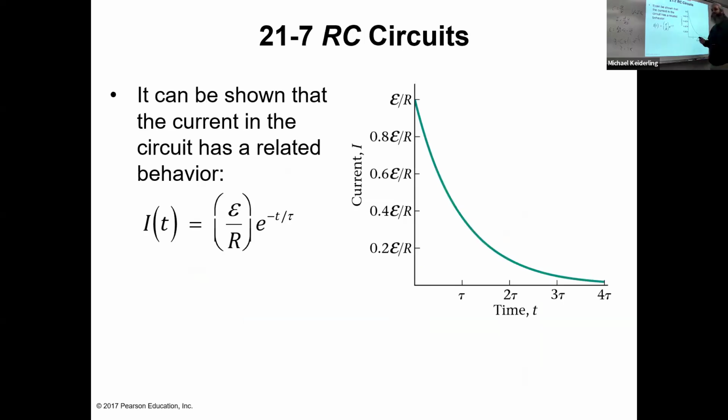And so you can set up situations where you have one thing with a relatively high resistance that charges a capacitor up slowly. Maybe that's the internal resistance of your battery. And then you have a setup where your capacitor discharges very quickly through something with a low resistance that you want to pump out a lot of energy very quickly, like a flash bulb. If you've ever used an old camera with a capacitor charged flash bulb, it takes time, like those disposable cameras, you have to hold down the button for the flash. That's charging a capacitor, which then discharges.